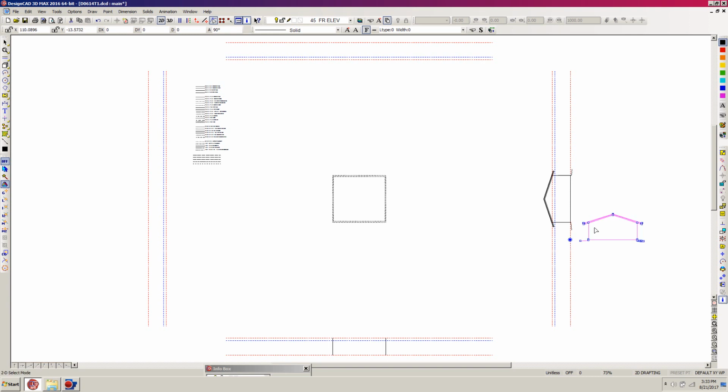And now I'm going to hit M for Move, and I'm just going to bring this on down, and all I have to do is hit K and snap to this floor line. So I want to get it fairly close to our drawing here. And actually, I think I'll just K right about here. K. Okay, so now what it's done is it has given us some height information as far as concerning our roof and our gutters and all of that.